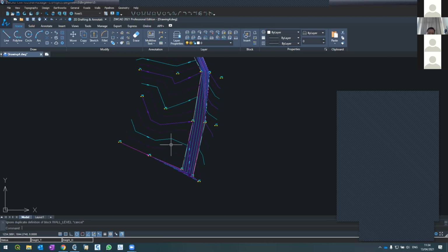I'm resurveying the area and I have the new coordinates file of this area. After the cut and fill has been done, meaning we have the surface before, now we'll create another surface which is after. And then we'll tell the software to compare the two surfaces.